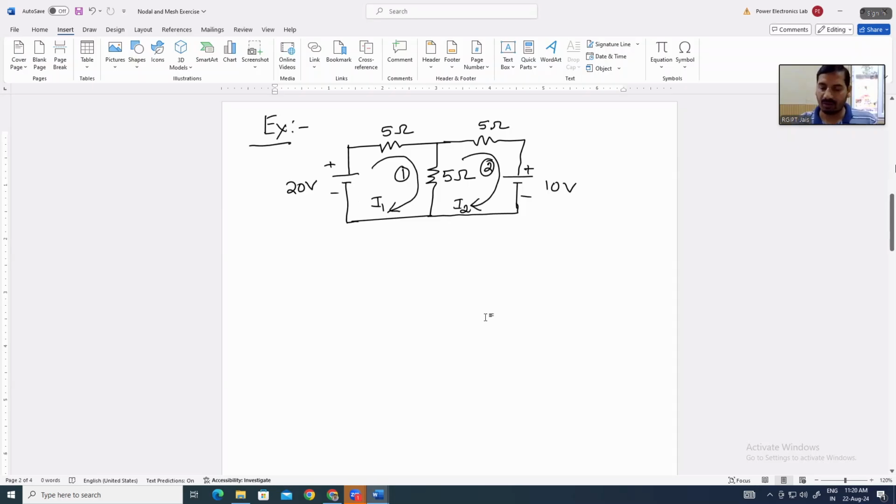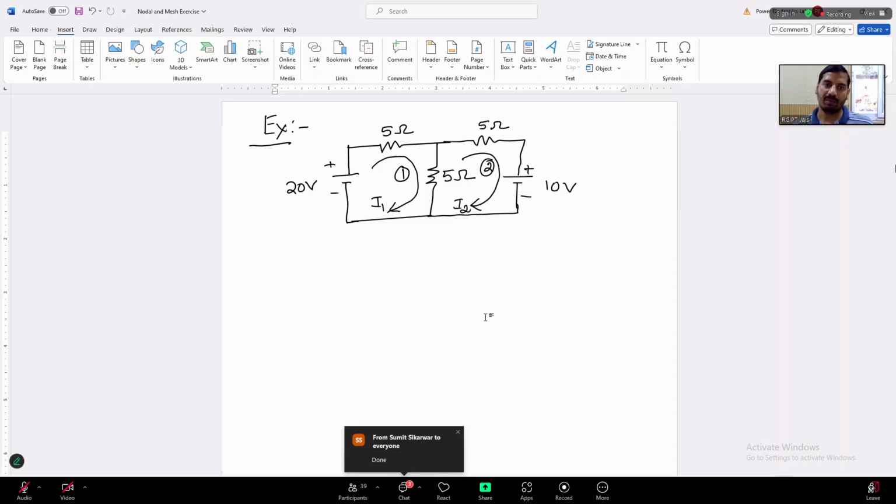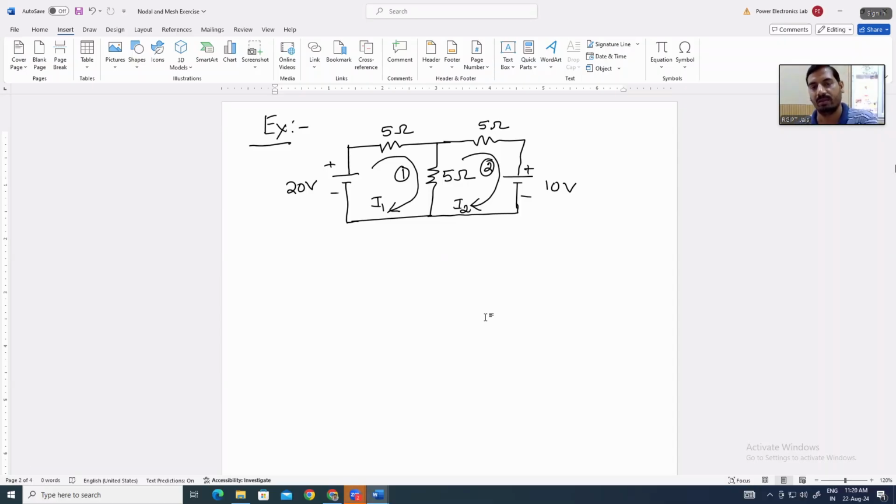So you can also try to write down this circuit, and in your copy make the loop currents in the clockwise direction, denote the loop currents I1, I2 in the two loops, loop 1 and loop 2, and then apply KVL individually considering each loop. So in this mesh method, first we will apply KVL in loop 1.